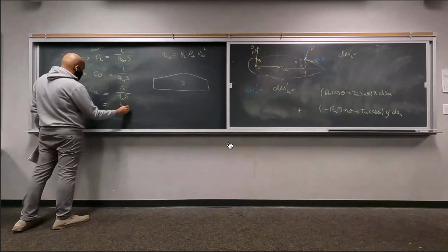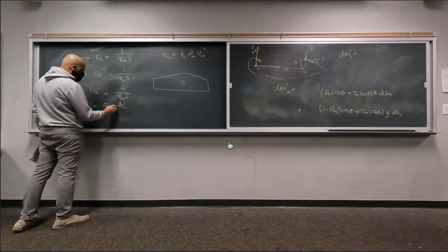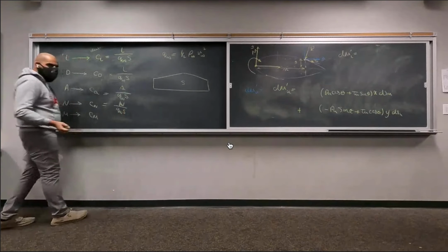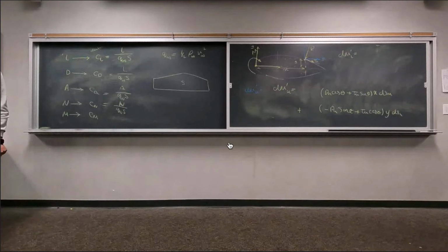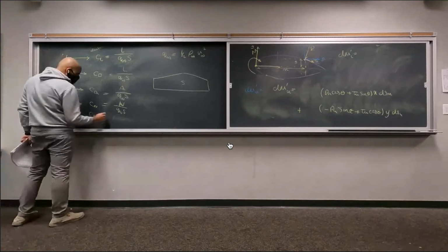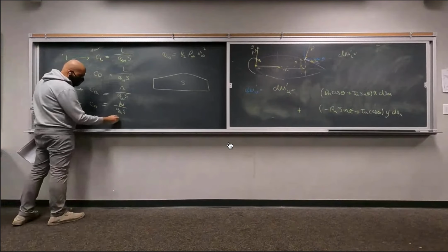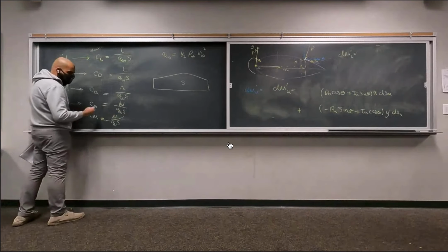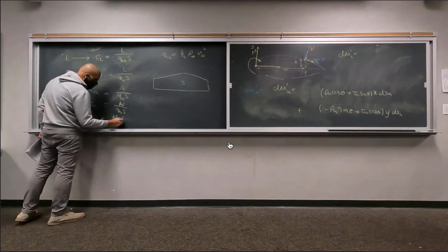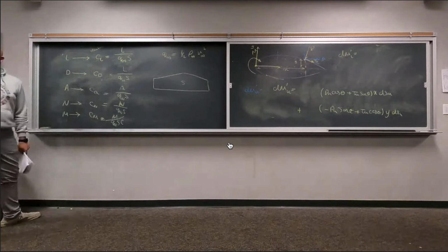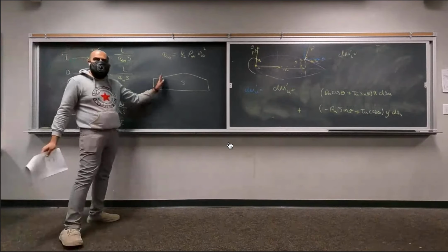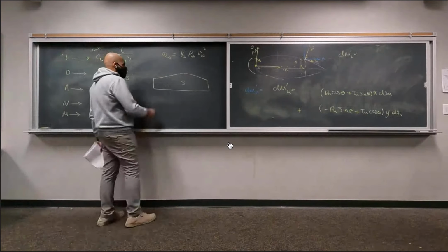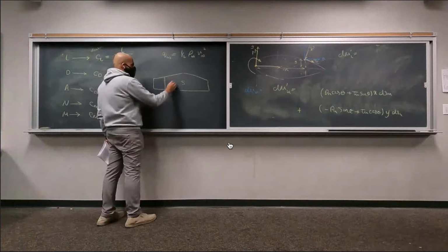But when it comes to moment, it's going to be a little different, because in moment we have the contribution of the R, right? The moment arm. So we are going to divide the moment by Q infinity to make it non-dimensional, multiplied by S, multiplied by a length. For the case of a wing, your length is going to be your mean chord. Again, this is a top view of the wing. It's going to be your span area, and your chord length is going to be this.